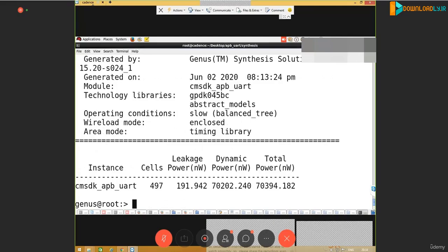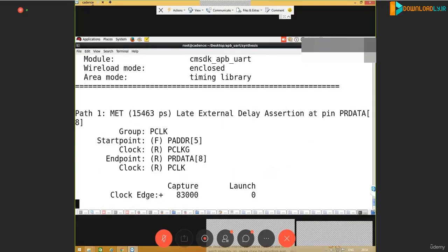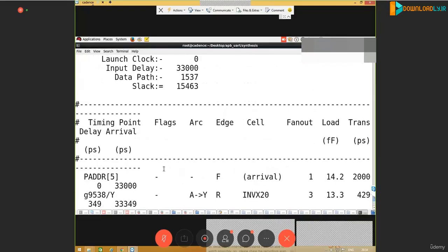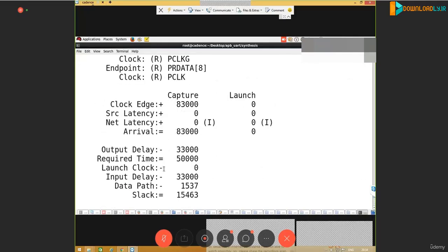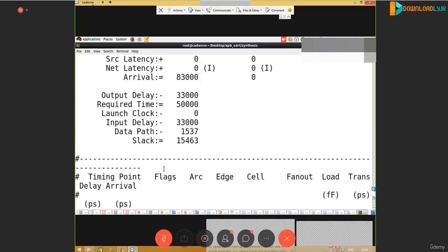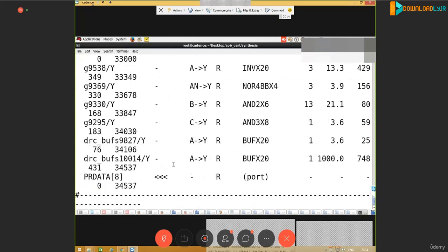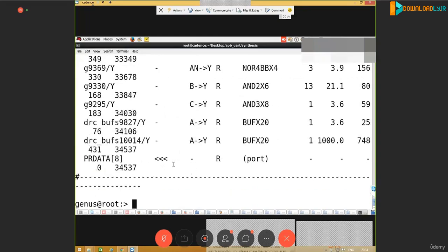And there is one more report that we need to generate, that is timing. So report_timing is the command to generate the timing report. This timing report, you can get a clear idea of when we enter into STA. As of now, it is not so required. We'll discuss the timing report part in the STA session so that you'll get a clear idea there. So the three commands are basically report timing, report power and report gates. These three are the report commands we are writing out.